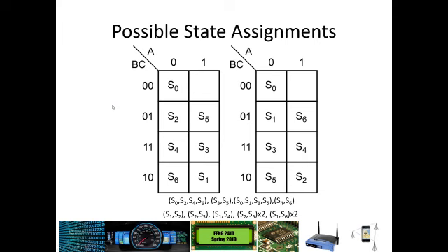And now, what this would mean is state S2 on the left side would be represented by 0, 0, 1, state S3, 1, 1, 1, S1 would be 1, 1, 0, etc. And so let's look, based upon these two possible state representations, and see which of these we were able to achieve based upon our guideline 1 and 2.